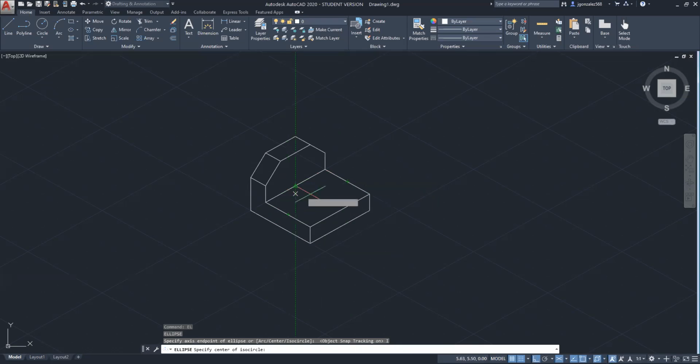0.5, based on the current units that we're using, some default ones. So 0.5. See how the circle grew out in this direction, which means it's mimicking the plane it's on. So ISO circle means draw this direction. If you don't choose ISO circle, it might draw a circle in a strange way. It might be going up and down instead of this way, or left to right, etc. Okay, so take advantage of the ISO perspectives.